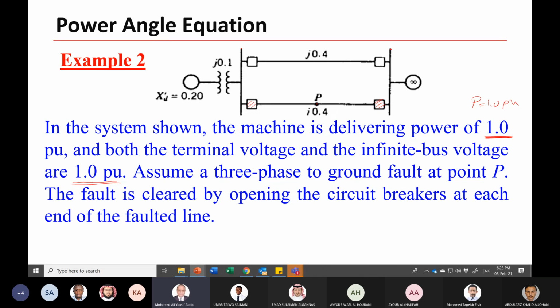So you have different configurations. Pre-fault, the system has two lines. During the fault, we have a three-phase short circuit here, as we discussed a few minutes ago. And to clear the fault, we isolate the line, so you have another configuration with only this line here.